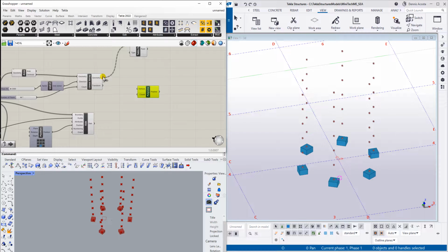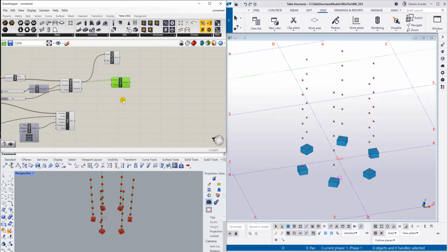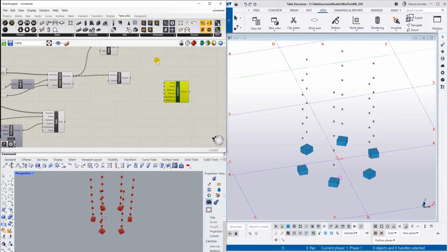So look, if I click the polyline here, geometry to vertices, see, there will be a line here. Now, I need to use this polyline and add the column. So for the column, I can use now the steel column here. Let's put the column, and then before I link this polyline, I want to make sure that I add the attributes here.